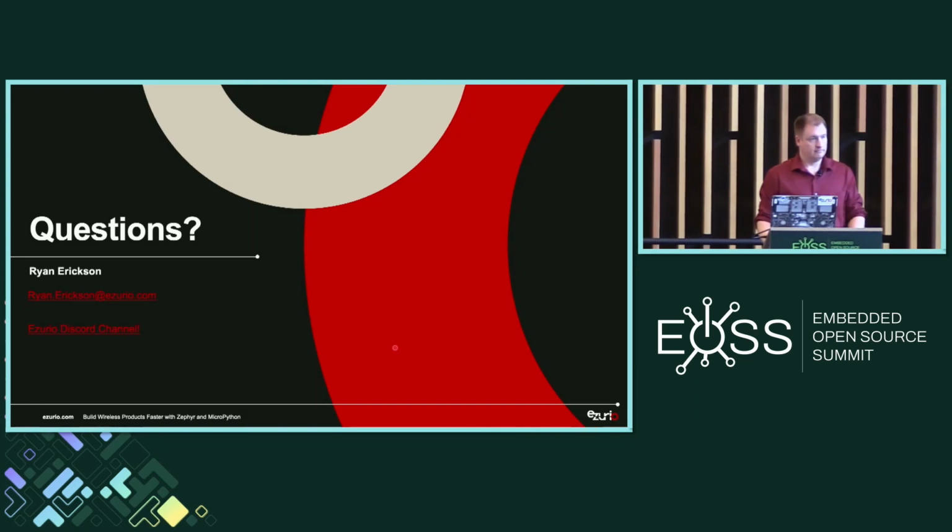So right now, we're providing that core firmware image. It's not open source, so we will be rolling out new firmware updates, so we will provide the binary. The binary is already signed. So with our desktop tools and our mobile app tools, we already have a way to easily just put the binary on there, and it will flash it over BLE or over UART for the user. But it's using standard protocols like the MCU Manager CLI could be used manually.